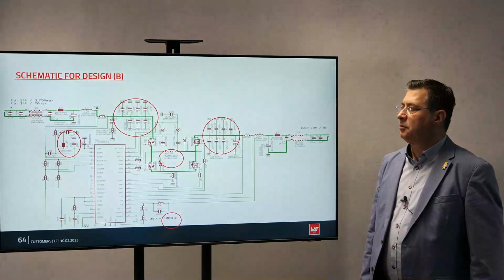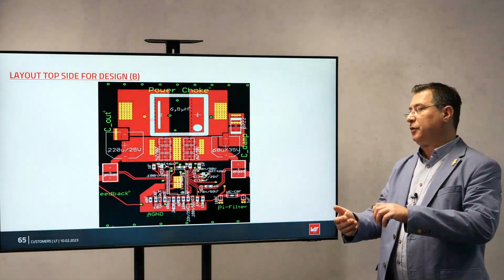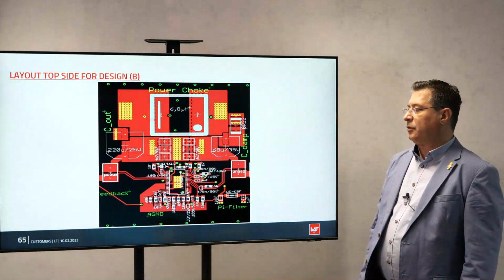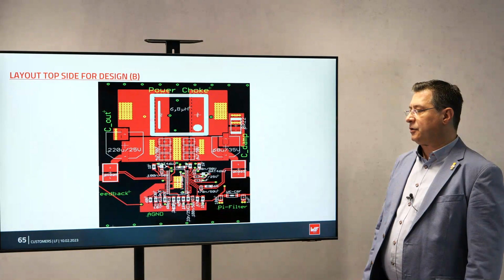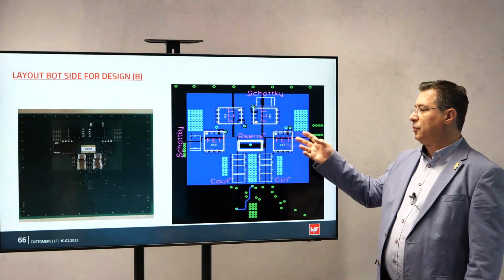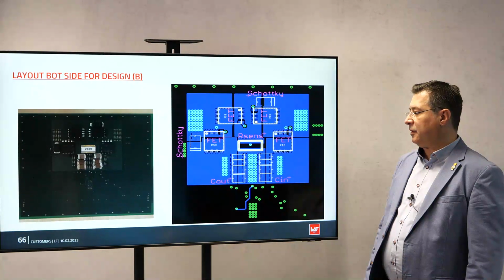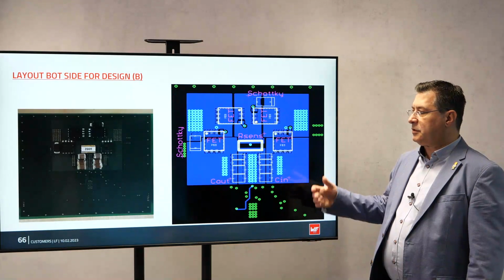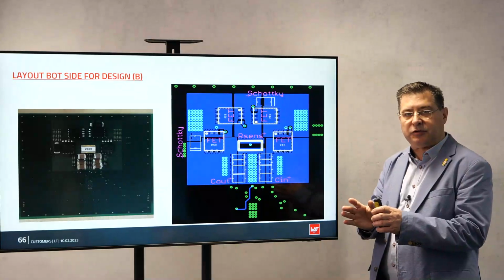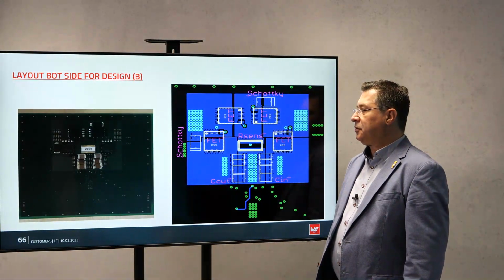And looks not bad. Make the PCB with 6 layers, components on the top, components on the bottom. Again, polygons for the big current, small current loops with one single connection to the main ground, and then on the bottom side, you put the FET, the current sense there, and some Schottky diodes as well. Well, that is how it looks, the capacitors on output and input very close to each other to not generate antennas, like I told you before. So that looks not bad.